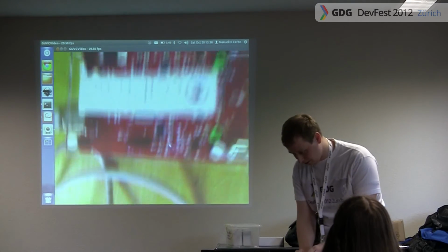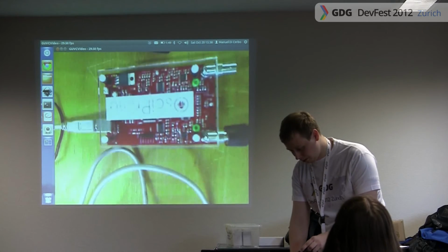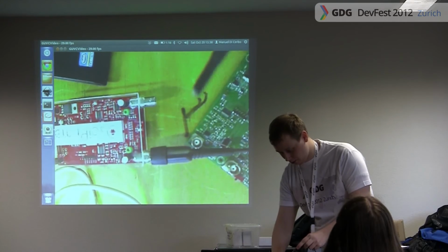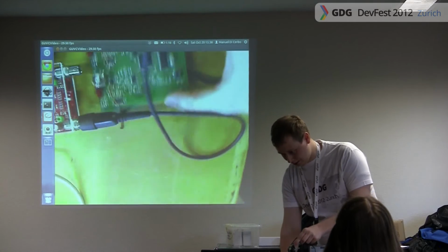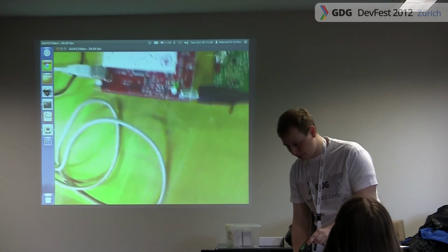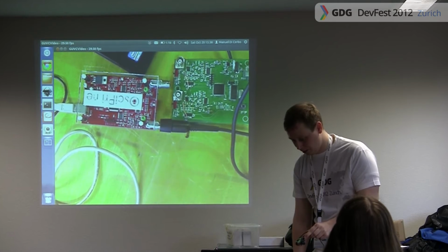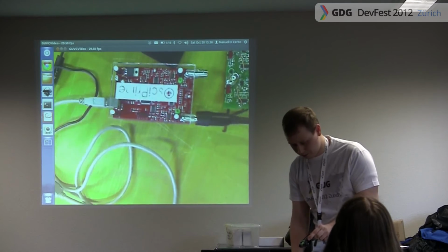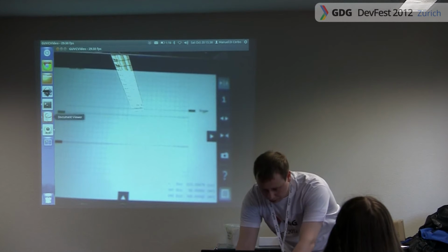Okay, so this is the hardware. You have a USB connector over here. You have the BNC connectors here and here. And you hook up a normal probe like this to the oscilloscope. And this over here is our prototype. You see we made quite some changes. The new layout is a lot smaller. It is also a 4-layer print. The prototype was a 2-layer print, and the prototype also had components on the back, which the new one doesn't. Okay, enough with the photos, and I'm going to slightly adjust the camera here.